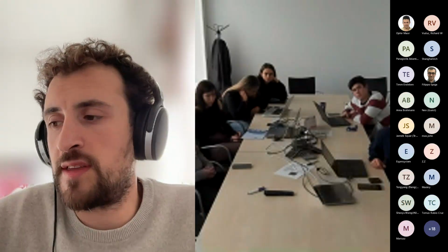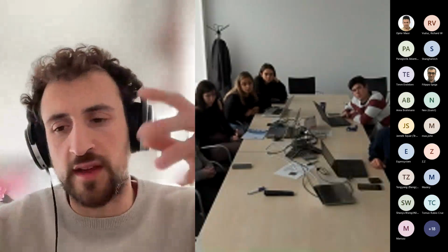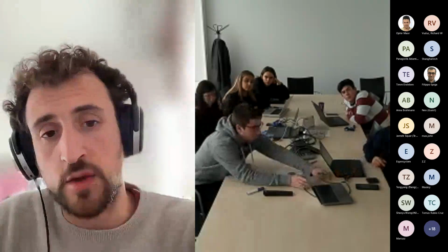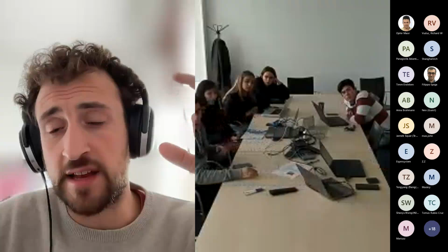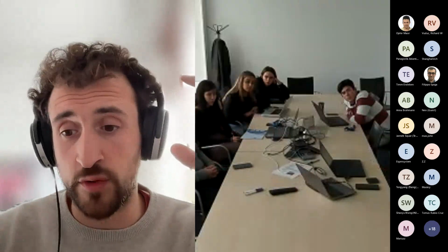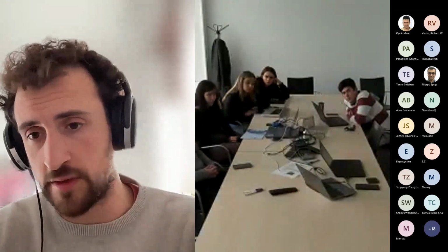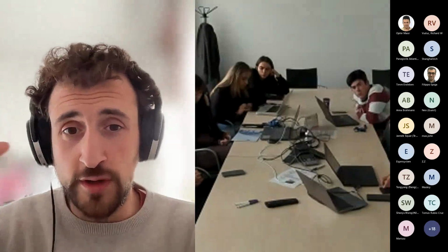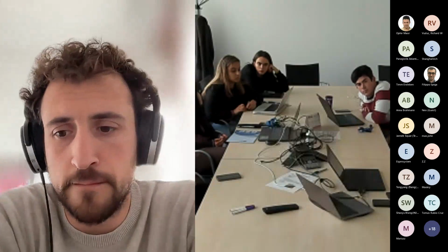Yes. Just to give you an idea, let's say the problem is a simple, homogeneous one. If you keep the L size fixed and you change the number of points per direction, you're basically increasing the resolution of the problem. You can try that, for example, if you want to do weak scaling. But keep in mind that if you do the same 100 time steps that we decided on, or whatever number of time steps you want, in order to have the same physical time as the other case, you have to roughly multiply the total number of time steps by 2. Make sense? Yeah. You can also tell me if it doesn't make sense, and I will explain it again. No, it's fine. Okay, perfect. Thank you.